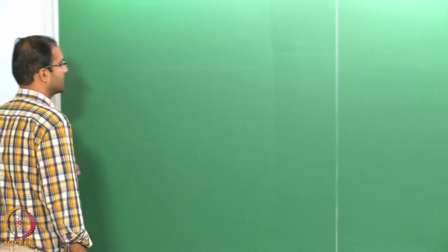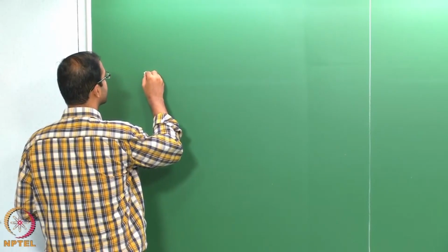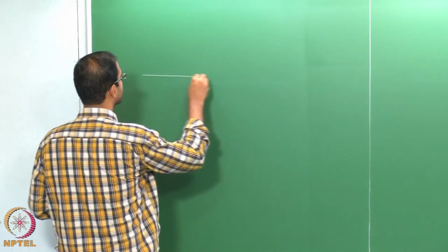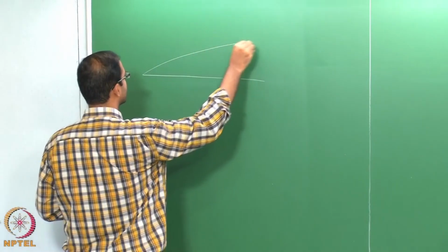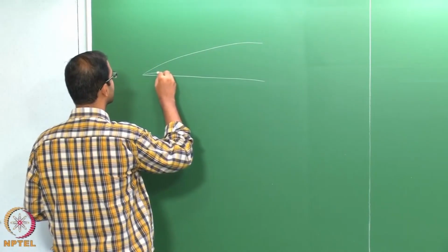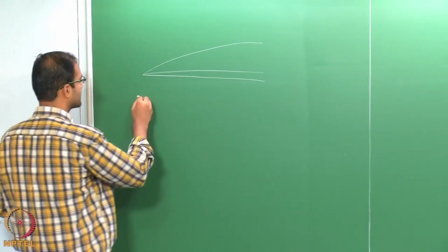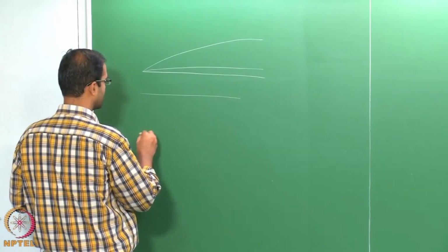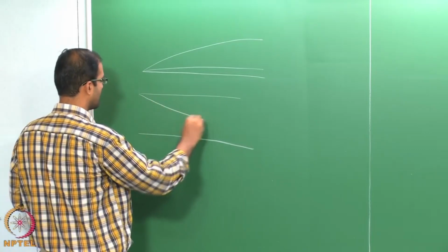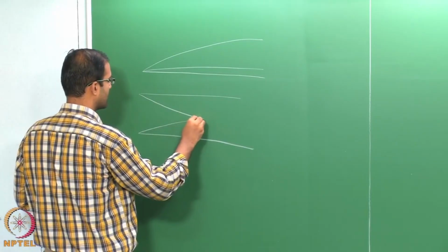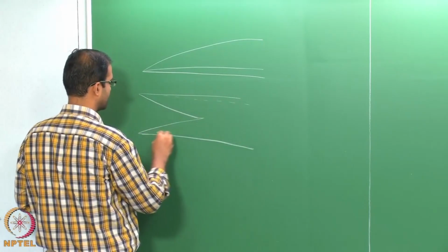within the boundary layer of a turbulent flow. Usually these are derived either for a simple case like flow past a flat plate, where you have the turbulent boundary layer and a sublayer, or for simple fully developed turbulent flow through a duct, where you talk about the boundary layers merging and also the growth of a small viscous sublayer.